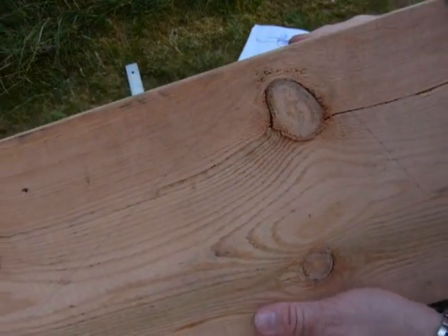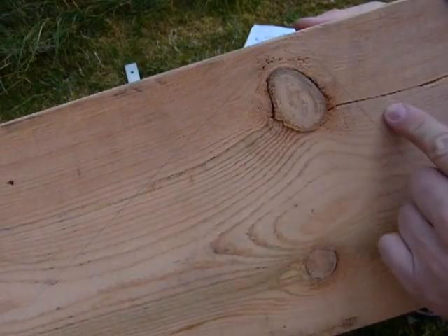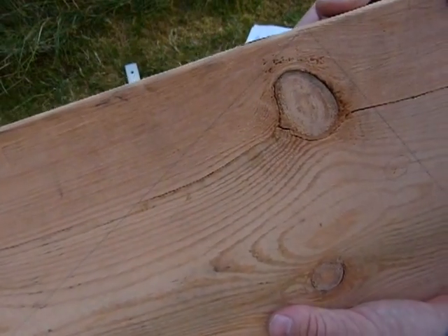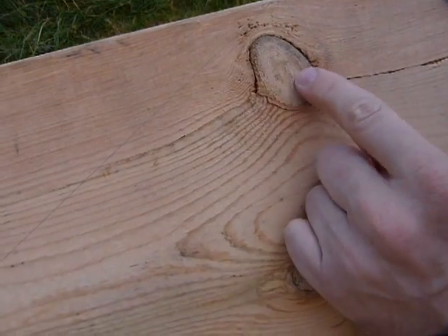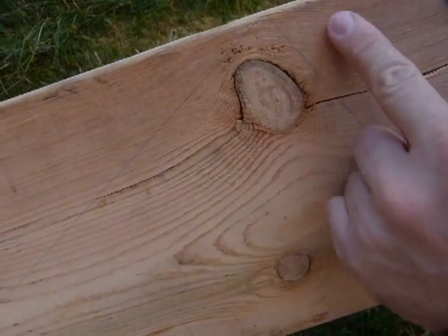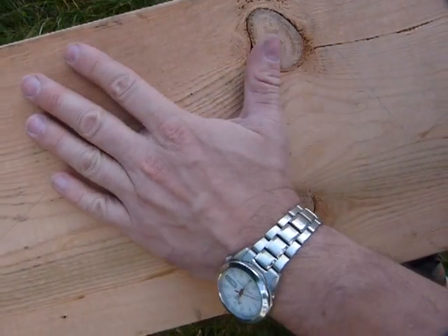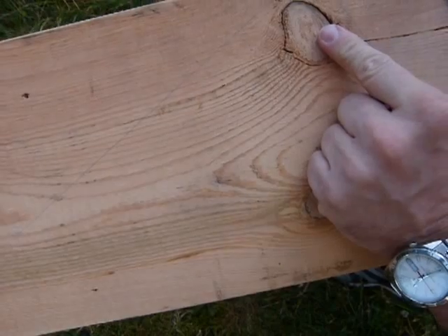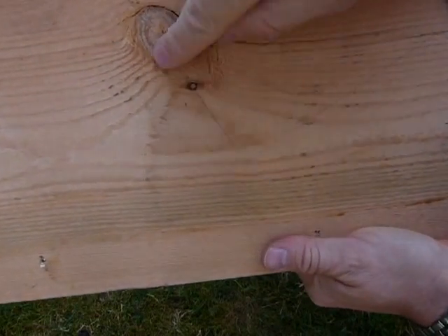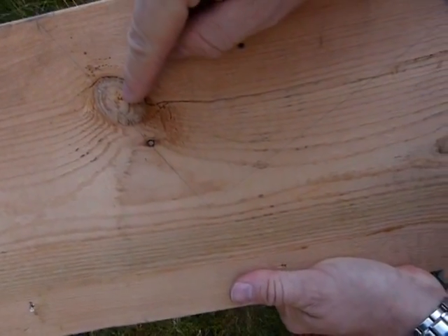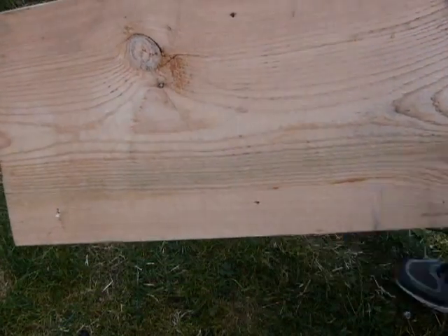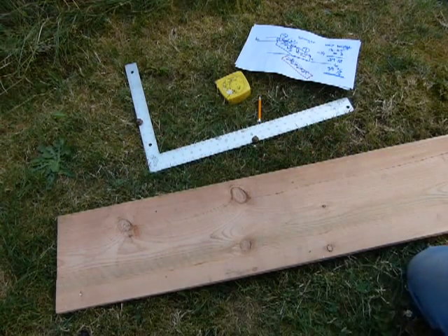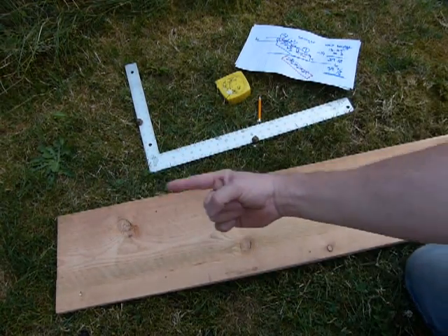Notice the knot here, you see my pencil line on the wood. This is the cutaway part, and this is the part that stays. The knot is still contained within the stair. It's not good. I'm gonna need to shift my whole layout in that direction 2 inches so that I can get rid of that knot, and also that one which I intersected halfway. So I would need to repeat the whole thing, but I'm not gonna do it. I'm just gonna finish this one. Just pretend those knots are not in the way anymore and everything has been shifted 2 inches in that direction, okay?